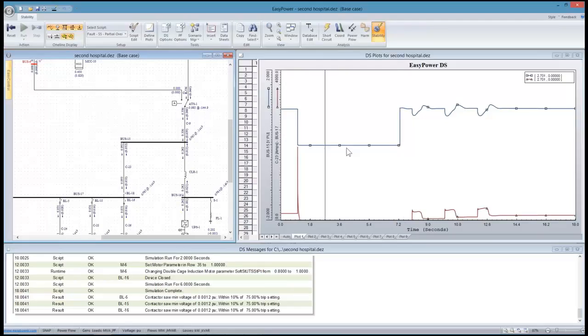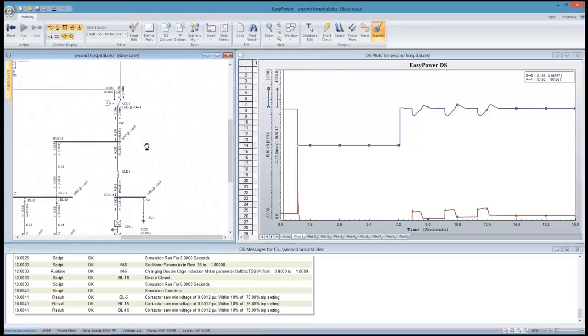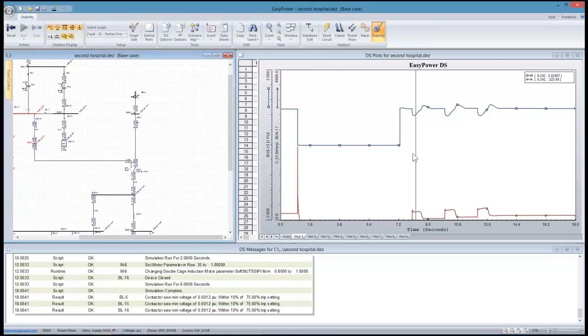We have a block of time that we run to let the ATS switch over and the generator get up to speed before we start turning the breakers on. Here we can see the result of each motor coming on the elevator, and then the 2 second delay, and then the next motor coming on.